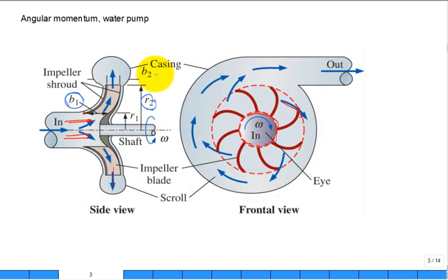Do they show you the B2? Here's the B2. It's kind of out here, right there. It's the height of the water passage on the discharge from the impellers. Maybe we should show it right here. That's B2. And this distance right here to right there is B1. The gap that it flows through. Right. So you can have typically B1's larger and then B2 is smaller.